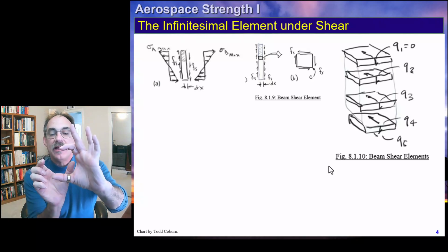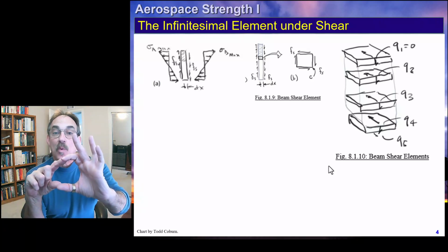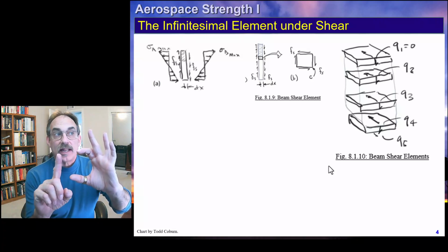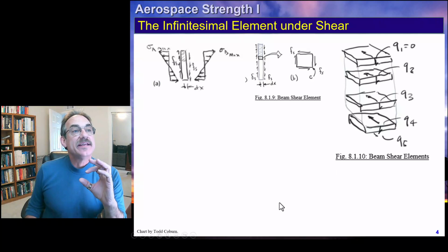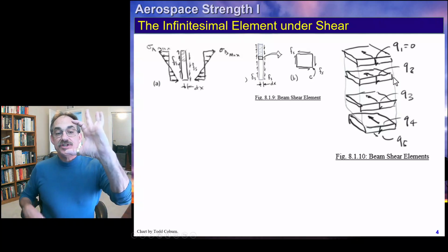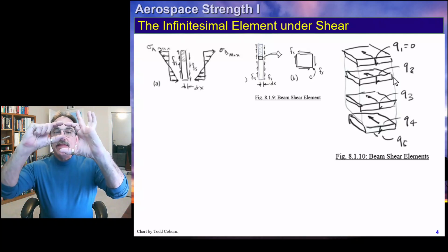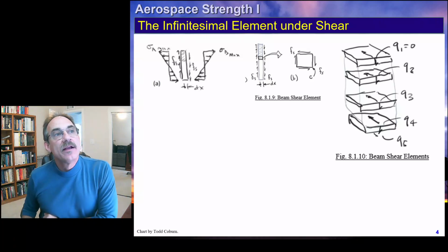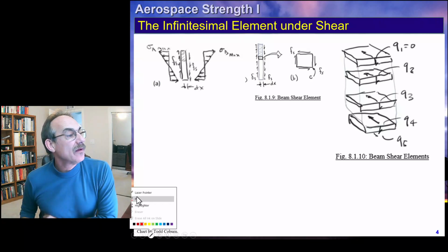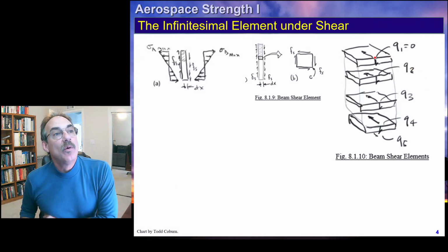Everything above that, the 1 inch width times the 1 inch height, is the area, times the Y position from the centroidal axis, which in this case, if this were 4 inches tall, would be 1.5 inches up, right? Because it's 2 inches, 2 inches here, and the middle of that 1 inch piece is at 1.5 inches. So we see that right up here, our area was 0, so our stress here is 0.